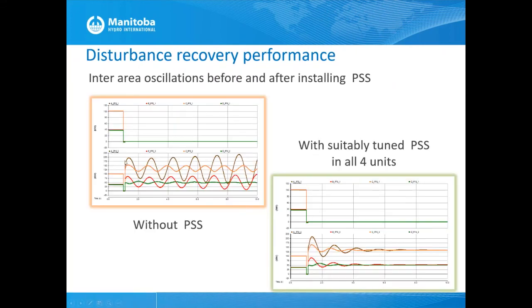So here, this has enough synchronizing torque, the torque which is proportional to delta delta. That's why, when there's a... actually, I'll show you an angle plot which I don't have right now. Let's assume this is the generator angle. You have seen this kind of oscillations. Let's assume these are all generator angles.